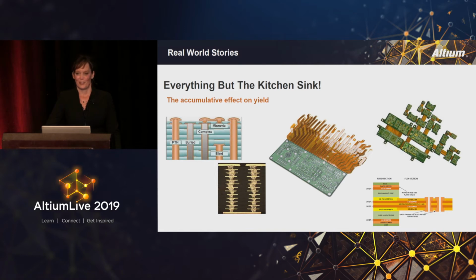And there's a little bit of truth to that, right? We all like to push the edges, and that's fine, absolutely fine to design to the edge. But when you design multiple attributes at the cutting edge, the accumulating factor on that yield goes up very quickly. They like to say, rough rule of thumb, for every attribute that you push to that leading edge, it's going to be a yield hit of 3 to 5, 7%, something like that at that leading edge.